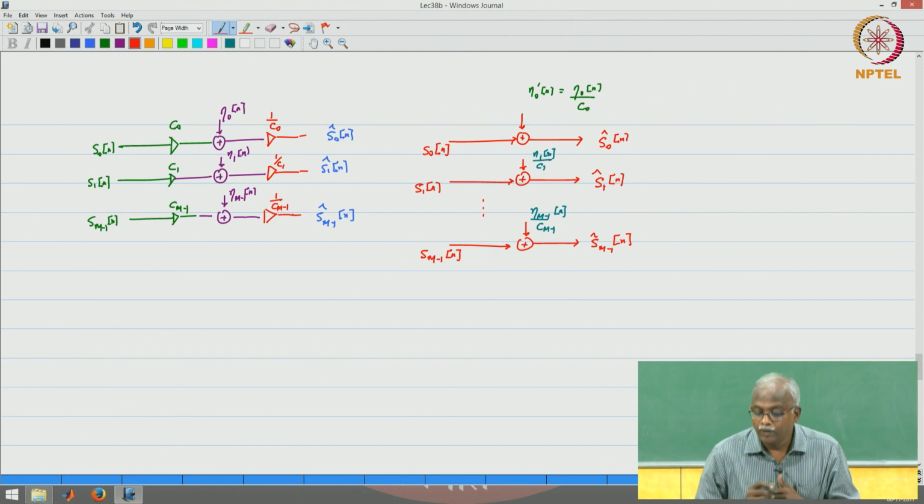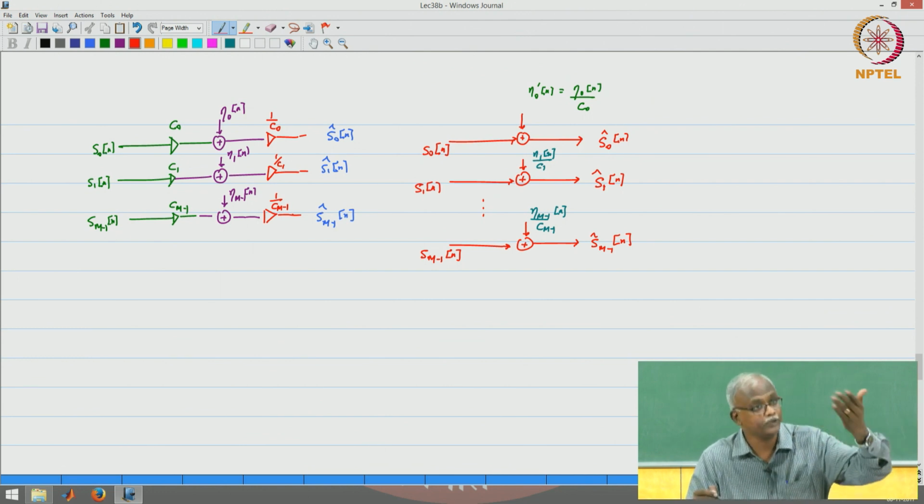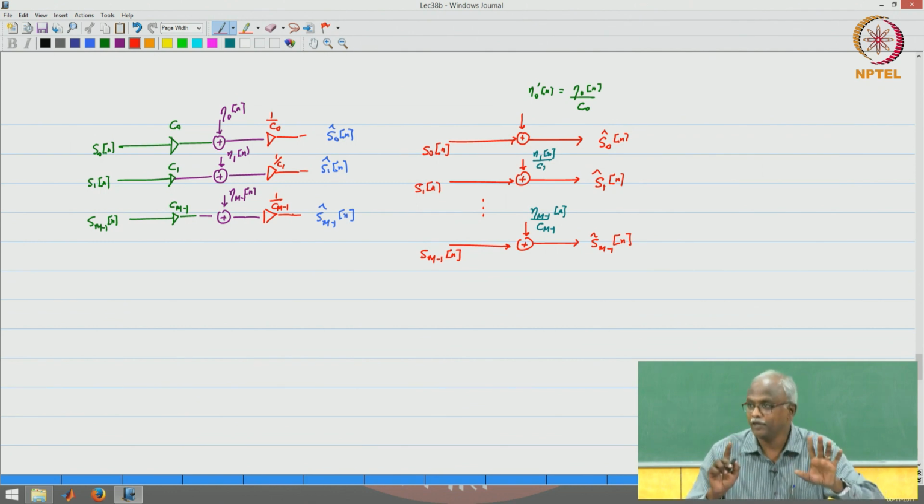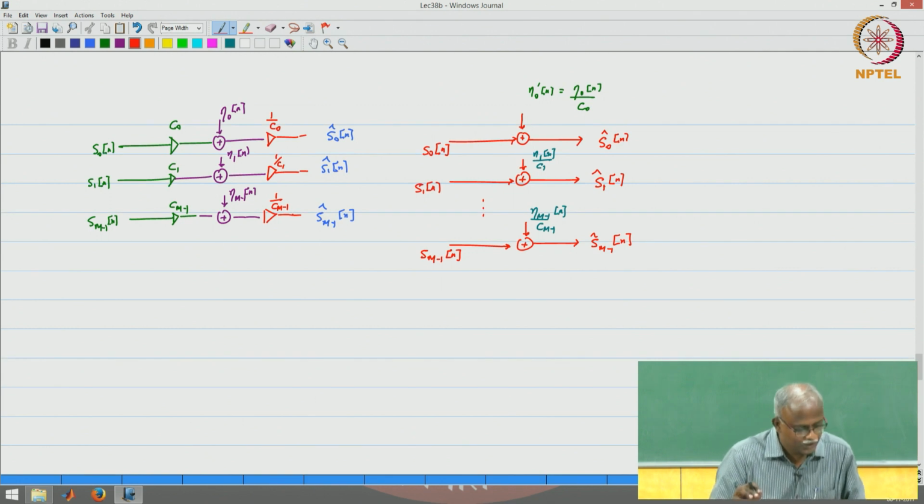And now what tells you that you can transmit on channel 0 and not on channel number 1? What is it that will make you decide one way or the other? Value of C naught. Okay, if C naught is very small, what will happen? It looks like that particular channel has got a lot of noise because C naught is in the denominator, and your power allocation algorithm would have said, hey, don't waste your power transmitting on this channel, remove that from the equation. So basically you are having an advantage over that. So this is OFDM. This is in a nutshell the big advantage with OFDM and how we look at the complete thing. So let us summarize.